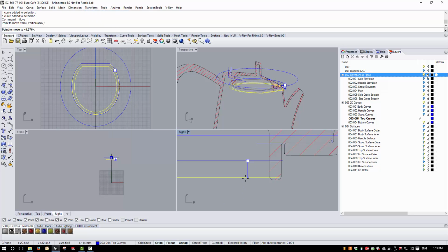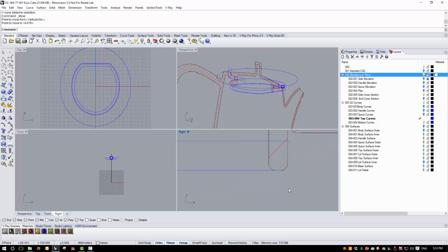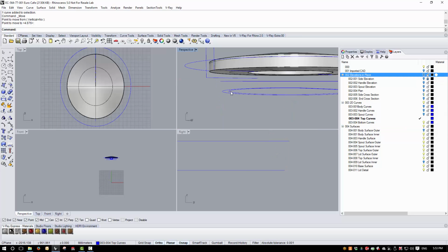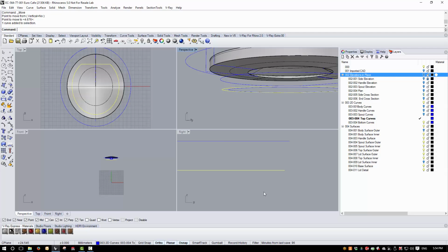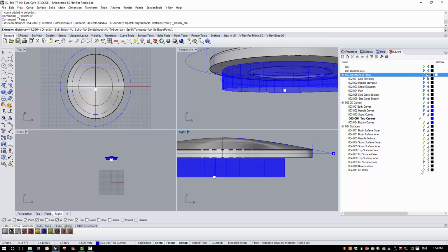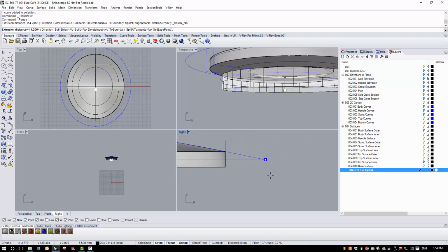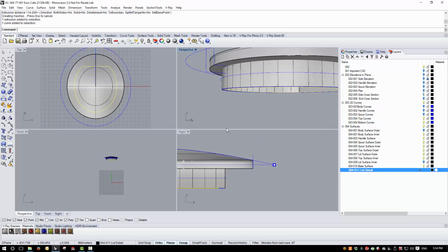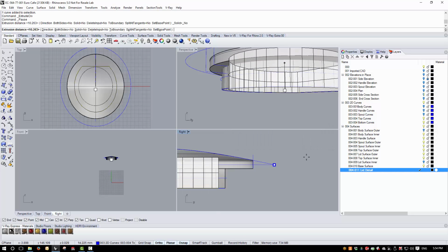So I'm going to use the move tool, hit tab to constrain the direction, and then snap to here. Then I can turn on my surfaces, turn off my elevations in place, and I can pick the outer of the two offsets here and use extrude surface with the extrude curve with the straight option. Make sure I do this on the right layer and pull this upwards, just make it slightly overlong, and then take the inner curve, which is here, and extrude this up slightly higher.